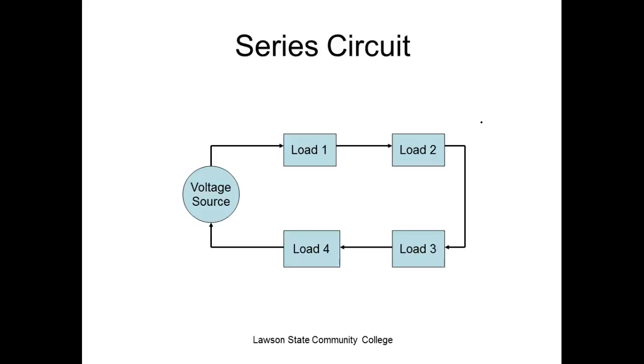And the loads are what? In series. So what happens if one of the loads opens? Well, if one of the loads opens, then we end up with an open circuit. If one of the loads shorts, we end up with a short. It's very important in the trade, when you get out in the field. These people can call it anything they want to, as long as you understand the difference between an open and a short. Very important.